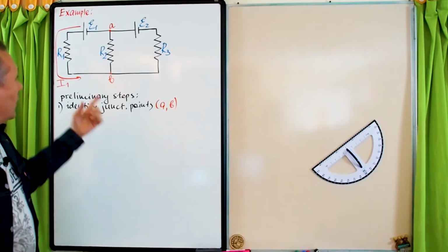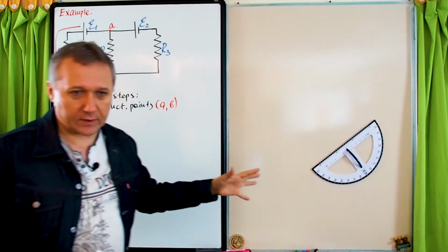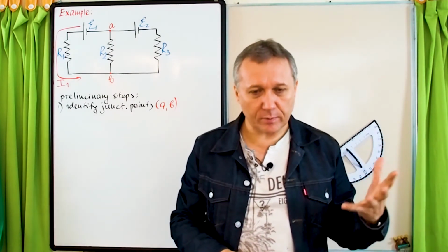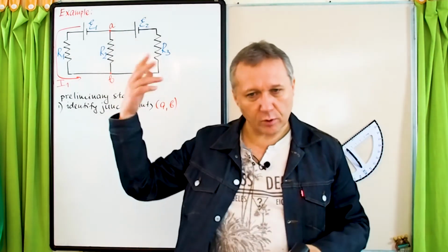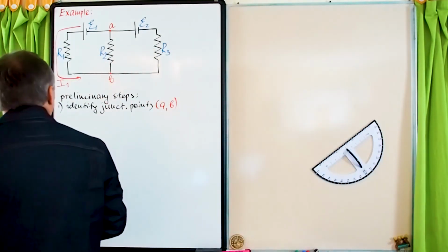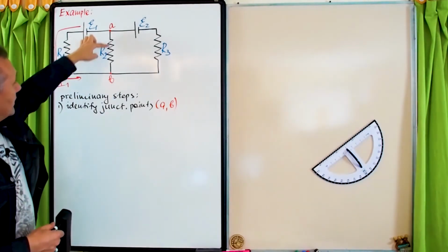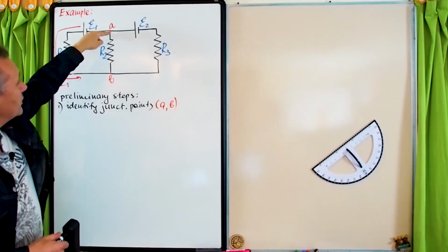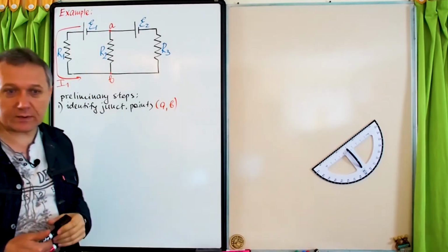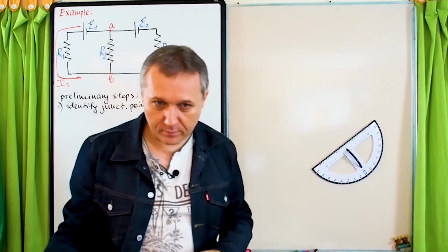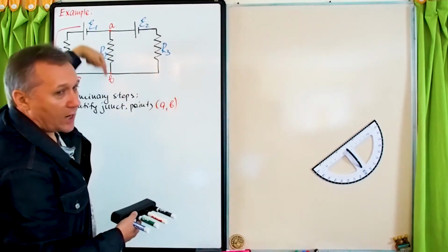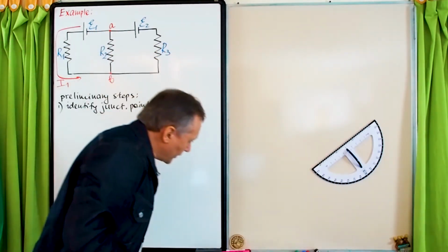Again, I1 between point A and point B in this part. You could have picked the other direction. Nothing wrong with that. Don't think about directions in this type of problem. Just pick a direction, solve the problem, and at the end, you will adjust it if needed. Okay, so the first current. Now, this part of the circuit between points A and B, again, there are no junction points, so current must be the same. Let's label it I2. Direction up or down doesn't matter. I picked up.